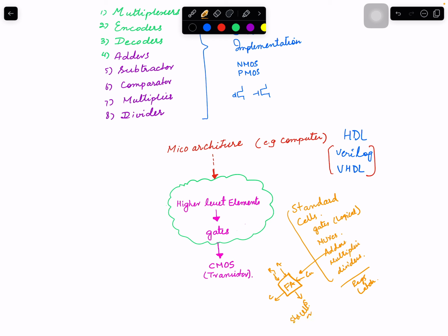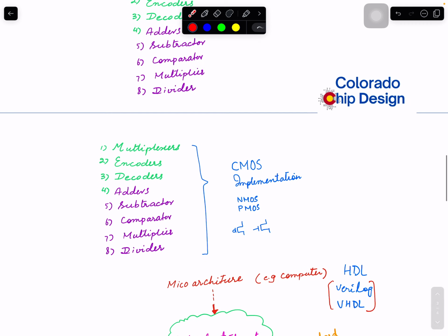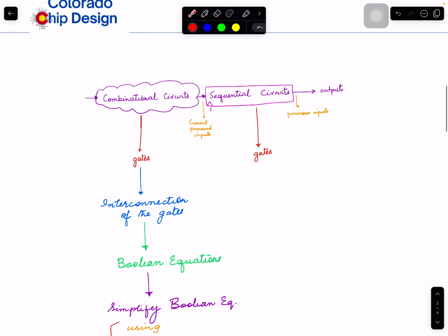And then when I take this RTL, I will use synthesis tools. Synthesis tools are going to convert this microarchitecture into standard cells. And for standard cells, I already have a layout version using optimized transistors. So you see the methodology that we are using, from RTL, down through synthesis, down to standard cells, and what we get is a netlist of standard cells. Then from the netlist we create a layout. We verify timing, design rule checks, and layout, and all those types of things, which we'll cover under physical design. Hopefully this gives you an overview of the bigger picture that we have.